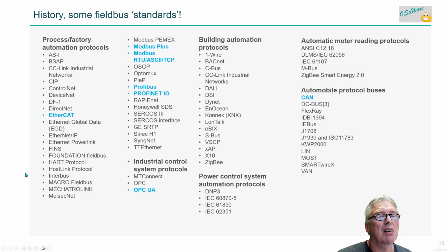And here is the mess. I've highlighted EtherCAT because it's innovative and really fast. Register insertion, we had Modbus and these. They are old legacy, but they are still around. This is old Siemens stuff, and Profinet IO is the new one. OPC UA, we're going to bet on OPC UA because that's going to be a standard.